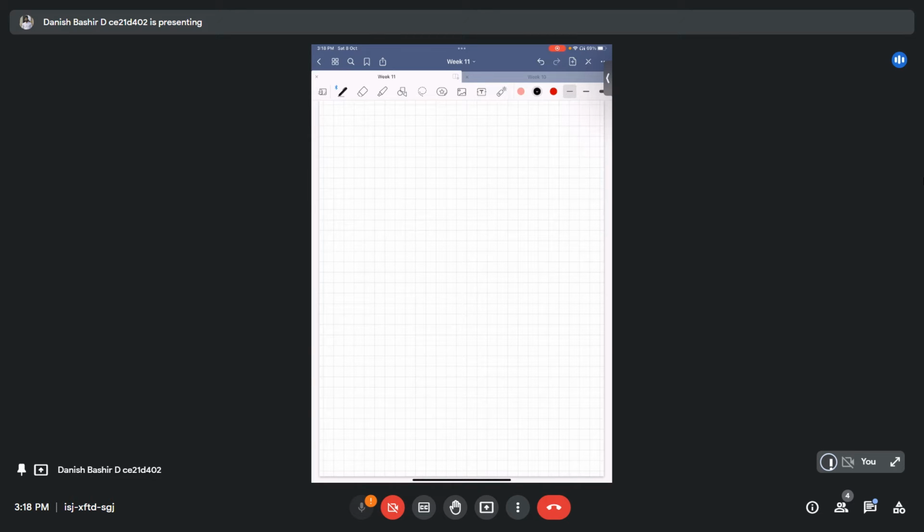Now we will have to check whether this section is adequate in terms of carrying this moment, because we have to check whether this 459 kilonewton meter is less than its ultimate limiting moment or not. If it is not, then we have to redesign the section, because we cannot cross the limiting moment capacity. Otherwise, we have to design the section once again, or go for a doubly reinforced section. So we will see whether R1 is less than Mu limiting by BD square or not.